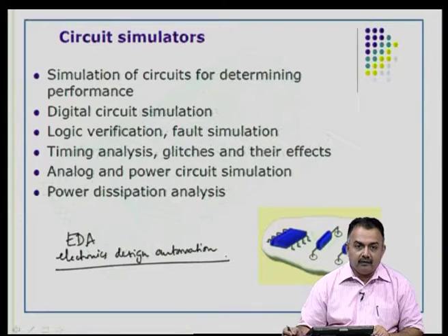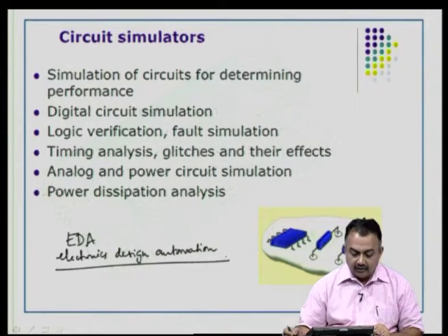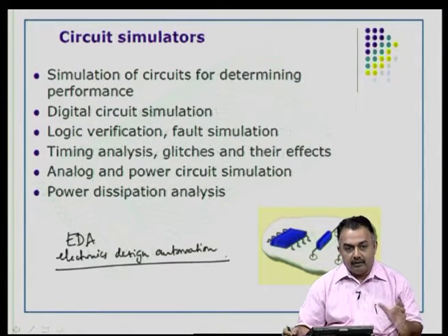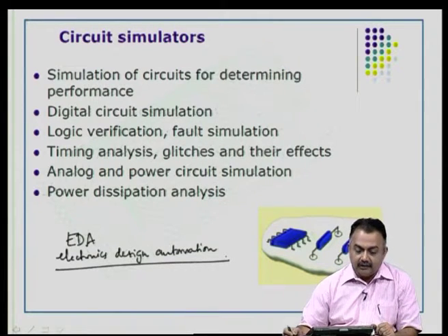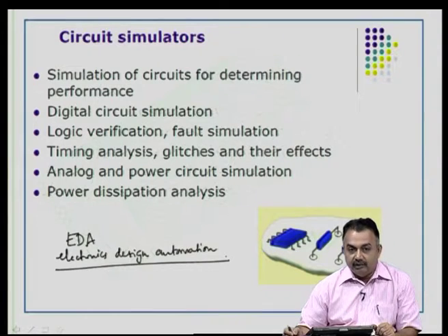A circuit simulator will have simulation for circuits for determining the electrical performance. You can do a digital circuit simulation, logic verification and fault simulation. You can do timing analysis of a particular net, glitches in the net and their effects. You can minimize these parasitics.